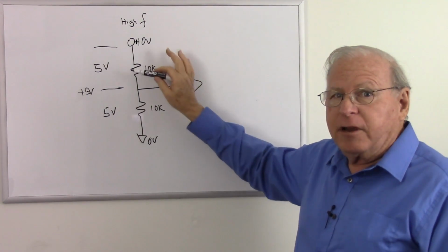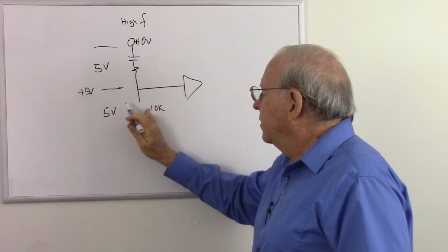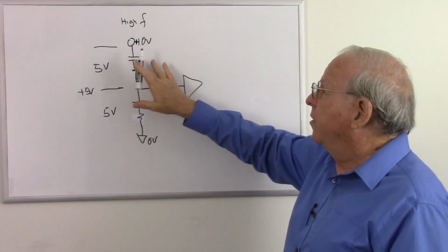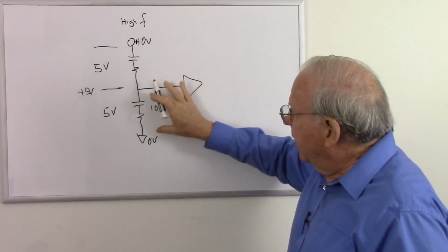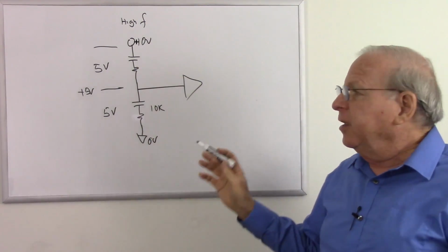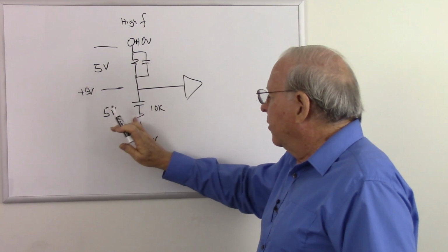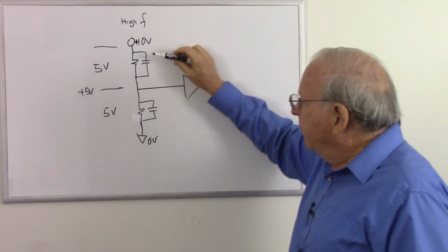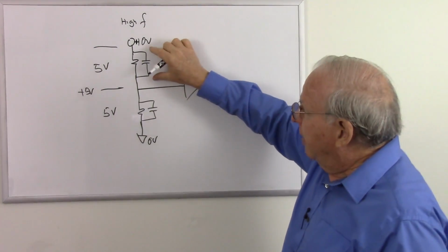So if these are the same configuration, let's draw them back as a capacitor and a resistor. Regardless of the frequency, they will both have the same impedance. So at low frequencies, they may have one impedance. High frequencies, they may have another impedance, but they will be the same at any particular frequency. So this will not even act as a filter. No matter what the frequency, we will get the same voltage division. So whether we make them in series or in parallel, if they are the same configuration, we will not get any kind of filtering, because no matter what the frequency, we will still have the same voltage division. It's still same impedance, same impedance.